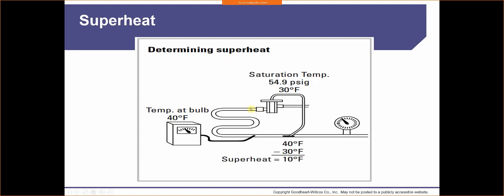As that liquid refrigerant starts to travel through, we have a steady stream of air being blown across it. All right, so this is our evaporator. Heat starts to get absorbed into the refrigerant, and it starts to create this change of state, because we've taken our high-pressure liquid and turned it into a low-pressure liquid at its saturation point. So we have that ability to go from either a vapor to a liquid or a liquid to a vapor.